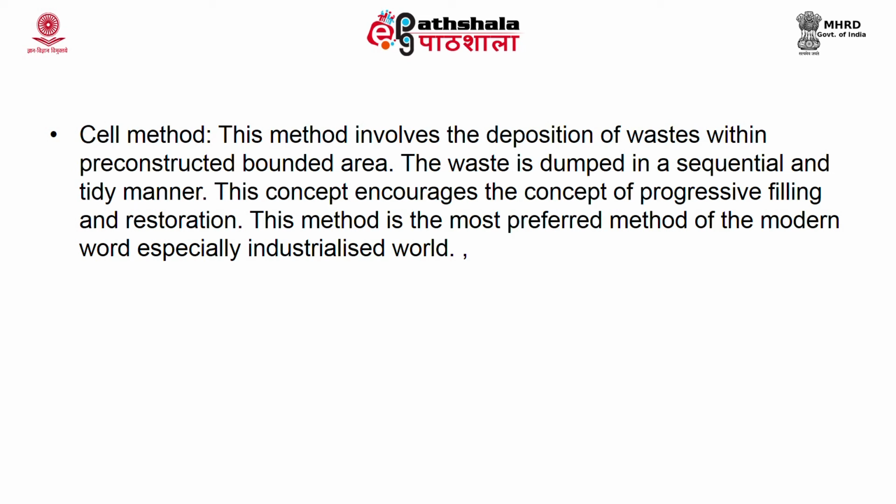So, this method involves the deposition of waste within a pre-constructed bounded area. It is one of the most preferred methods in the industrialized world because it encourages the concept of progressive filling and also restoration. Operating a cellular method of filling will enable the waste to be deposited in a proper tidy manner, that is, in a sequence.